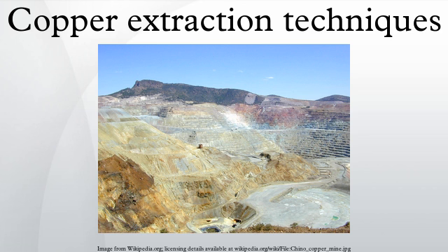As with oxide ores, solvent extraction and electrowinning technologies are used to recover the copper from the pregnant leach solution. Supergene sulfide ores rich in native copper minerals are refractory to treatment with sulfuric acid leaching on all practicable time scales, and the dense metal particles do not react with froth flotation media.